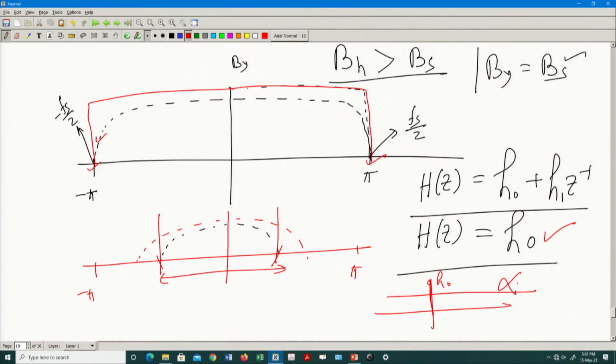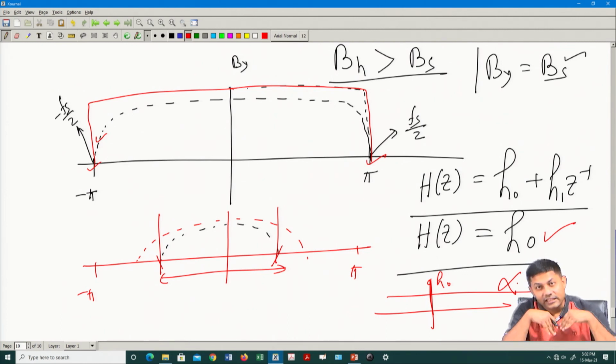It is not really infinite bandwidth. It simply says that within my viewing window, can a tap have an infinite bandwidth? Virtually impossible. You cannot have an infinite bandwidth of the channel. It all depends on how you sample it. Okay. So, if the channel is just like some sort of a multiplier or just a gain increment or decrement, of course gain will decrease, the channel will be viewed as an infinite bandwidth channel. It simply means that within the window I am looking at, the channel exists everywhere in that spectrum.